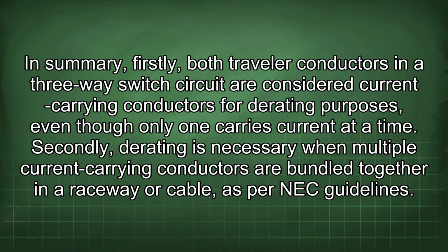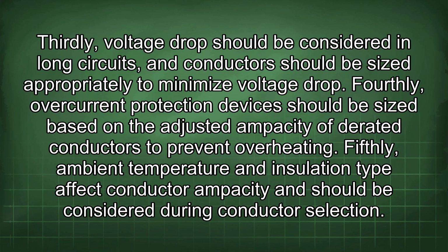In summary, firstly, both traveler conductors in a three-way switch circuit are considered current carrying conductors for derating purposes, even though only one carries current at a time. Secondly, derating is necessary when multiple current carrying conductors are bundled together in a raceway or cable, as per NEC guidelines. Thirdly, voltage drop should be considered in long circuits, and conductors should be sized appropriately to minimize voltage drop.